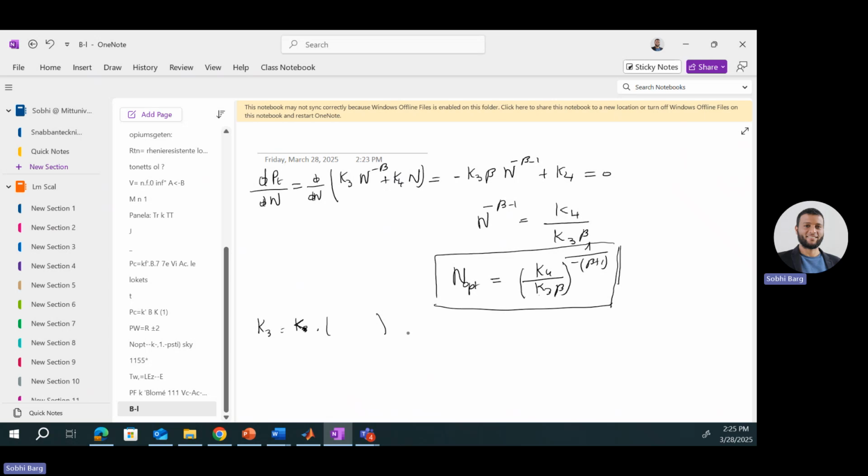That's the voltage, the frequency, and also you have alpha as the Steinmetz parameter. That alpha depends on the material, okay? And this K4 is just about the conductor specification. So it does not have any dependence on the magnetic material or the magnetic core. And beta is the Steinmetz parameter of your magnetic material.